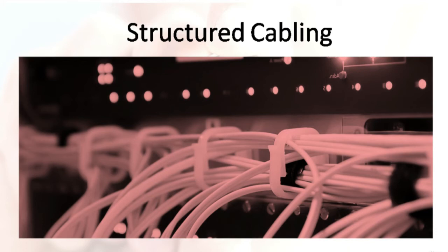For the cables, the most important parameter is its characteristic impedance, and these are split into categories as stated in the ISO standards. Without going any deeper, you only need to know that the only ones you need are category 6 or 7 cables, with the most prominent being 100 ohm characteristic impedance of these categories. If you want to learn more about this, you should get a copy of ISO 11801 for more information.